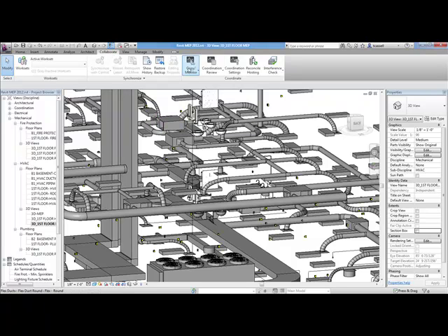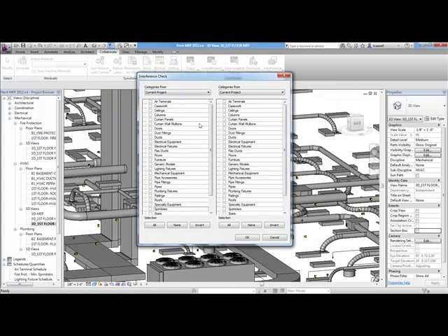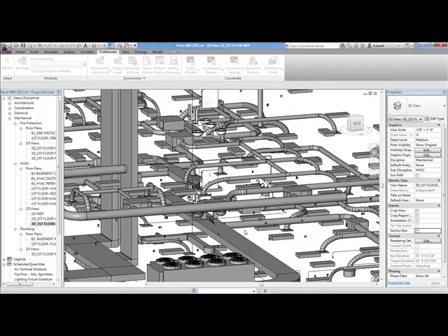The way we do that in Revit is we use a tool called interference check, and I can run an interference check on any object that happens to be in this model. So I can do maybe air terminals versus light fixtures. So I want to know if I accidentally placed any of my air terminals on lights. Now if I do this and I say okay, no, there were none.